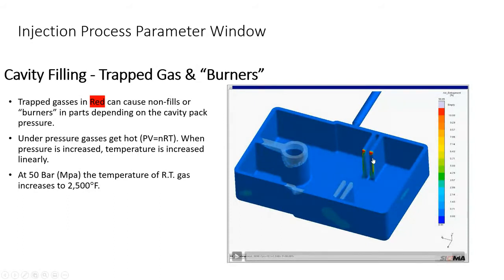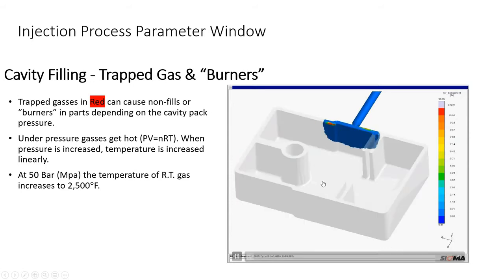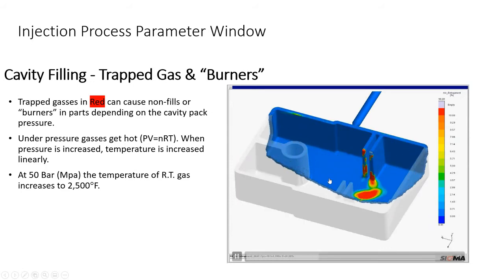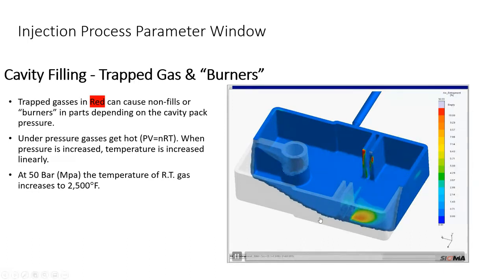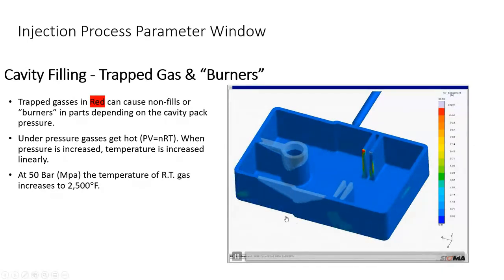You can vacuum the cavity. We always recommend in injection molding that we use vacuum. But what we see here is a place where the vacuum couldn't get to, and outgassing of the rubber created a pocket. That pocket is then put under higher and higher pressure as this cavity fills. It's low pressure, low pressure, low pressure, but then as this fills out and we hit that process window for filling the cavity, this becomes a high pressure area. And we have to understand something about the PV-T relationship.